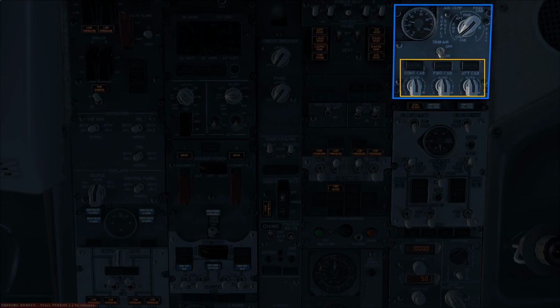back half. In the auto position, onboard computers automatically regulate various valves within the air conditioning system to regulate temperature within the aircraft. However, pilots can also manually select the temperature. The coldest setting is approximately 18 degrees Celsius, and the hottest is about 30 degrees.